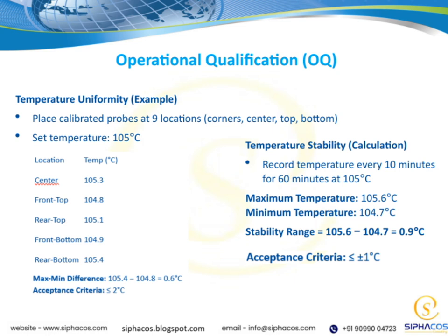for uniform processing. Finally, regarding operational qualification, or OQ, this process verifies that the temperature controls and uniformity meet specified requirements. It's about ensuring the equipment performs as intended and that the temperature is reliable and consistent across the entire chamber. This verification is a critical part of qualifying the system for routine operation and ensures quality and compliance in our